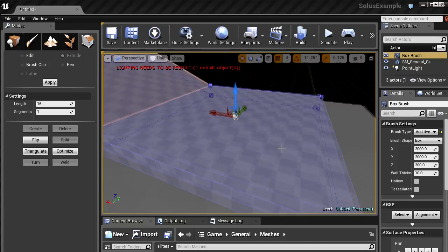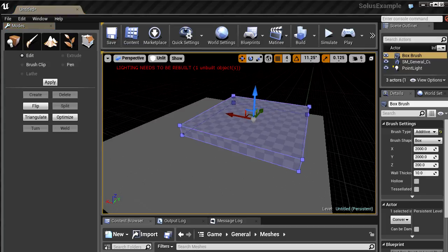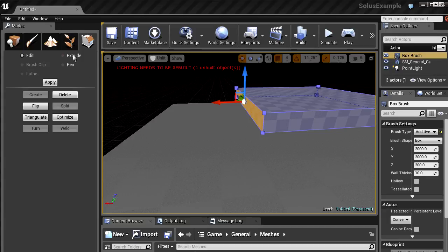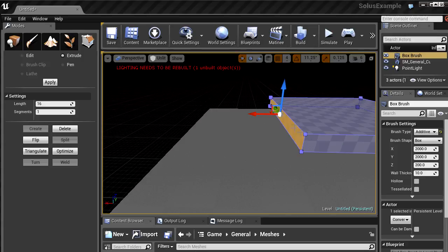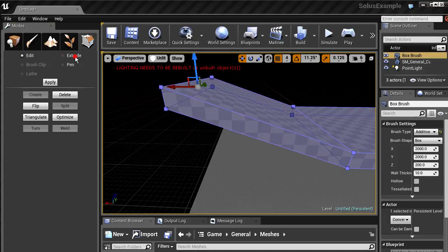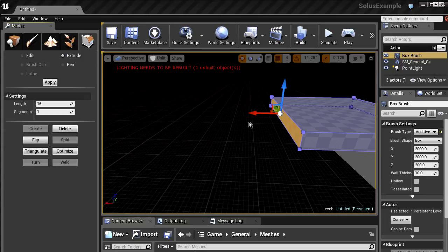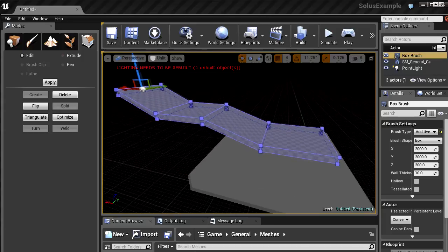Can very quickly do that again, just so it's clear. Place new box, and change the size if you want to. Go to Geometry Editing tab, click on one of the faces on the side, click the extrude option. If you get a warning about something, then the warning actually mentions this button over here, so it expects to be able to have this set to the little cube icon. Click and drag on the face, drag it out, click edit, up, click extrude again, drag it out, edit, or actually sorry, extrude again in this case because it's a flat area, up, etc.